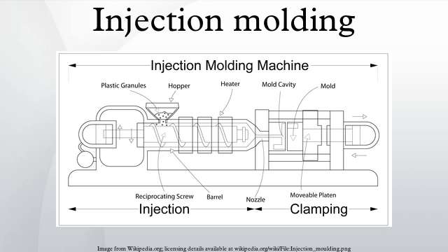The total clamp force needed is determined by the projected area of the part being molded. This projected area is multiplied by a clamp force of from 1.8 to 7.2 tons for each square centimeter of the projected areas. As a rule of thumb, 4 or 5 tons per square inch can be used for most products. If the plastic material is very stiff, it will require more injection pressure to fill the mold, and thus more clamp tonnage to hold the mold closed. The required force can also be determined by the material used and the size of the part. Larger parts require higher clamping force.